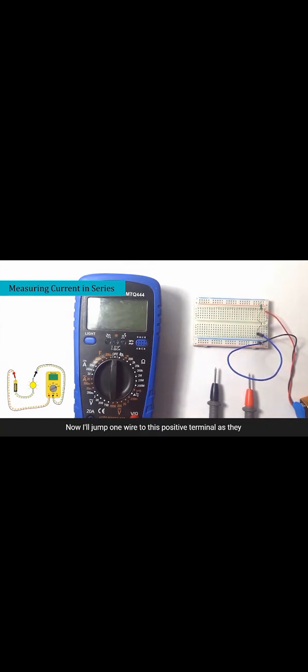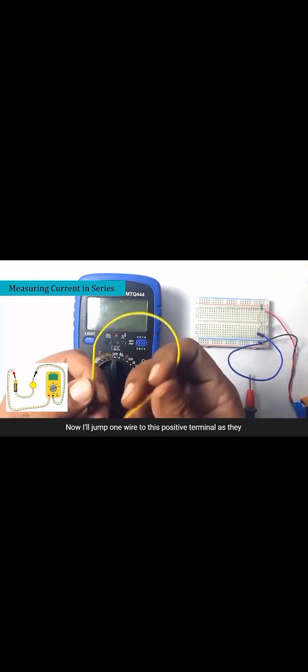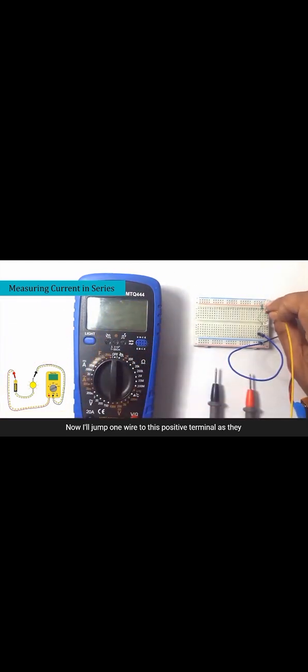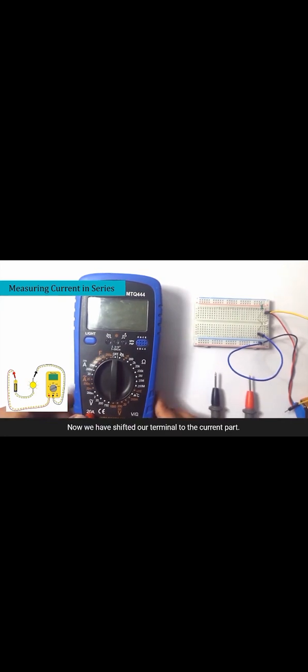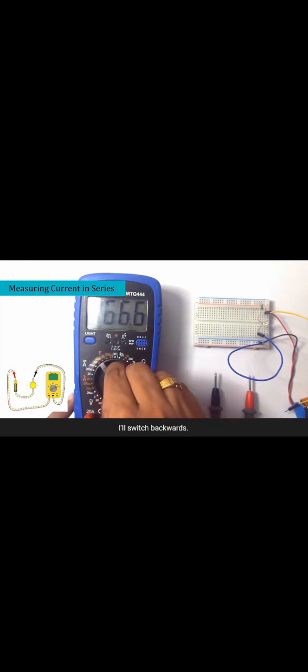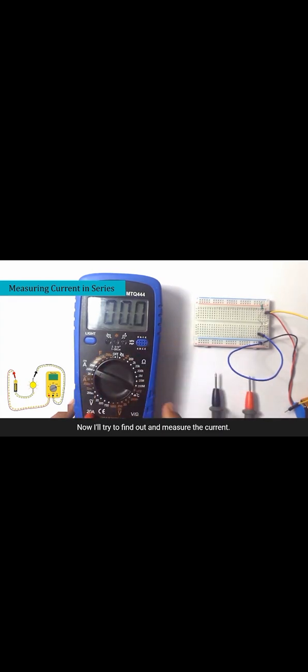Now I will jump one wire to this positive terminal. As these are connected vertically, now I can make the circuit in series. Before I connect the probe, I have to shift my terminal to the current part. Let's shift the terminal to the current part. Now we have shifted our terminal to the current part. Let's check the current. To check the current, I have to shift the knob to the DC current. I'll switch backward. Now I'll try to find out and measure the current.